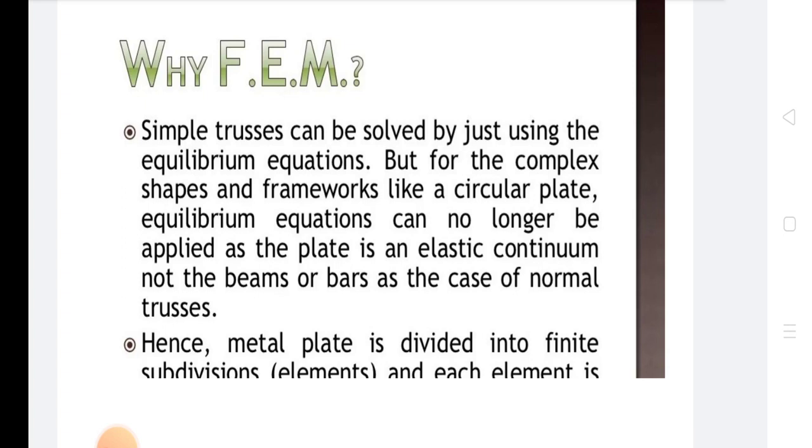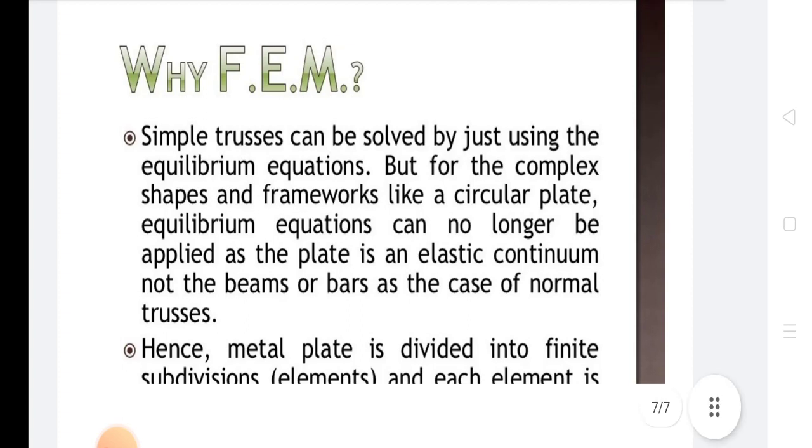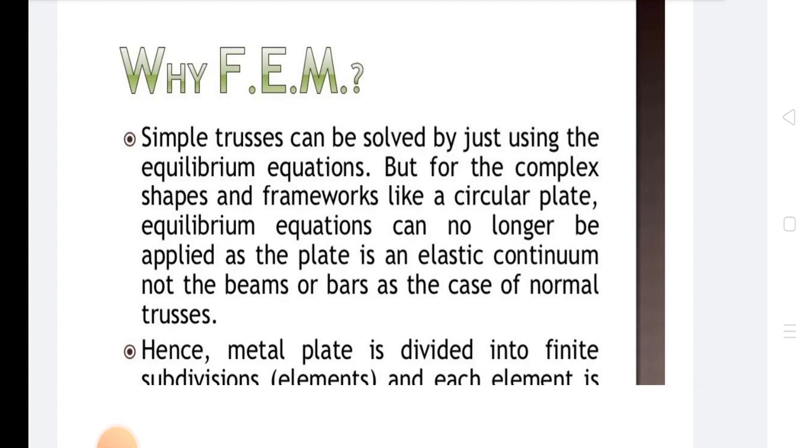In the finite element method, FEM makes a piecewise approximation. It ensures continuity at nodes as well as along the sides of the element. The solution can be obtained at the nodes as well as at any point within the field using shape functions. It needs fewer nodes to get good results. It can handle complex problems. It considers boundary shape as it is.